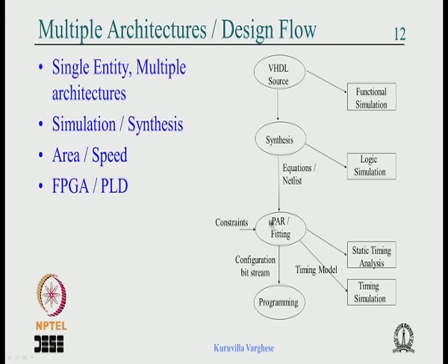So the minimum clock period can be specified. Depending on how you specify it, the place and route tool will keep the components closer, use shorter wires to interconnect, use the minimum number of switches to interconnect, and so on.